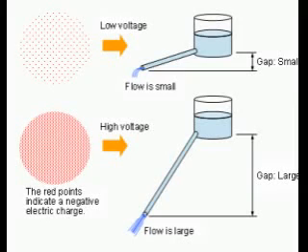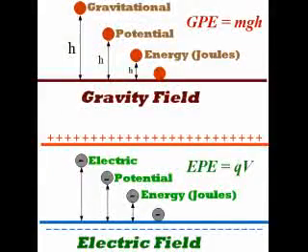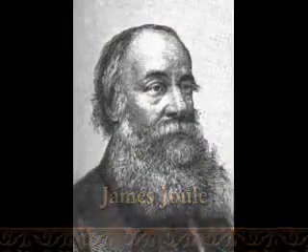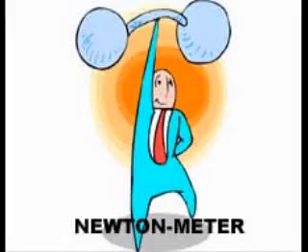As stated before, voltage is the measure of potential energy per unit charge available to motivate electrons from one point to another. Before we can precisely define what a volt is, we must understand how to measure the quantity we call potential energy. The general metric unit for energy of any kind is the joule, named after James Joule. It is equal to the amount of work performed by a force of 1 newton exerted through a motion of 1 meter in the same direction. In British units, this is slightly less than 3/4 of a pound of force exerted over a distance of 1 foot. Put in common terms, it takes about 1 joule of energy to lift 3/4 pound of weight 1 foot off the ground, or to drag something a distance of 1 foot using a parallel pulling force of 3/4 pounds.